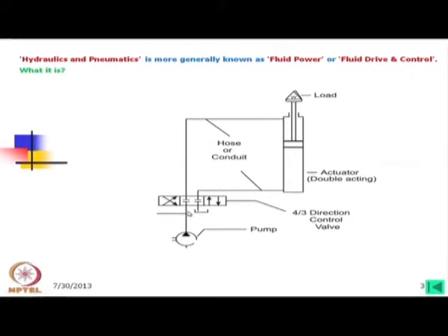and then if we looked into the left side of the direction control valve, then this pump will be connected to bottom, and there is a slight mistake in the arrow, then the top side will be connected to the drain and load will be lifted. Similarly, if we actuate this valve to right side, then this oil go to the drain and the oil will enter through the bottom, from the top, and load will come down.